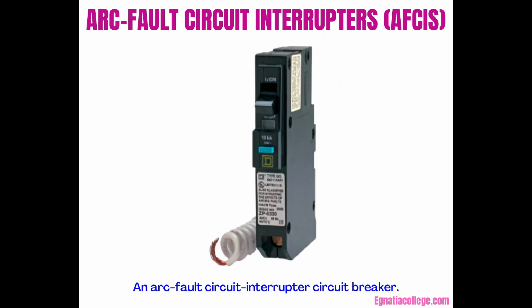Arc fault circuit interrupters, AFCIs. About 10% of fires are electrical fires. 1/3 of electrical fires are caused by arcing at poor connections or between conductors due to a breakdown in electrical insulation. For example, if the strands in a conductor of the cord for an electric iron break, a few strands may still be touching, and there may be enough of a path to permit current to flow.